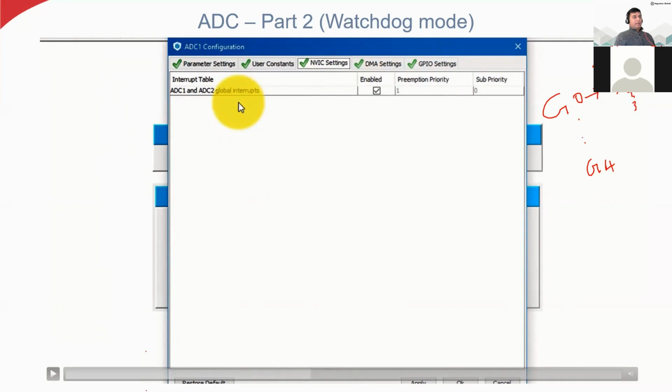And we also have the sub priority. For example, if you receive 2 interrupts at the same time, you have the CPU, you are receiving interrupt 1 with priority 0, and CPU will immediately execute this interrupt signal. And you are receiving another interrupt, this is I1 and this is I2, also with the same priority level.